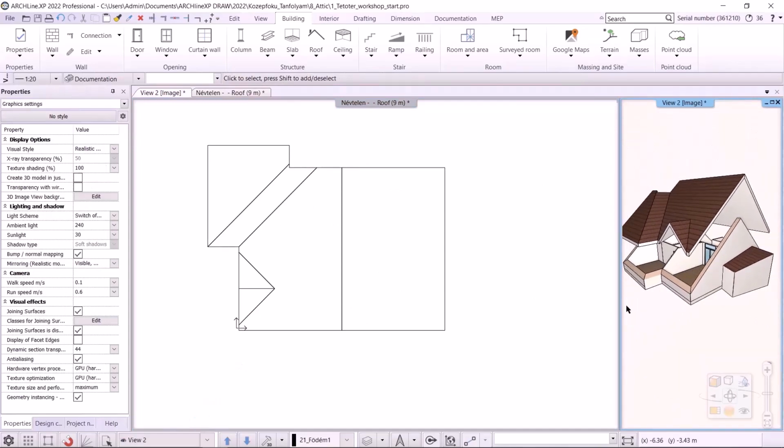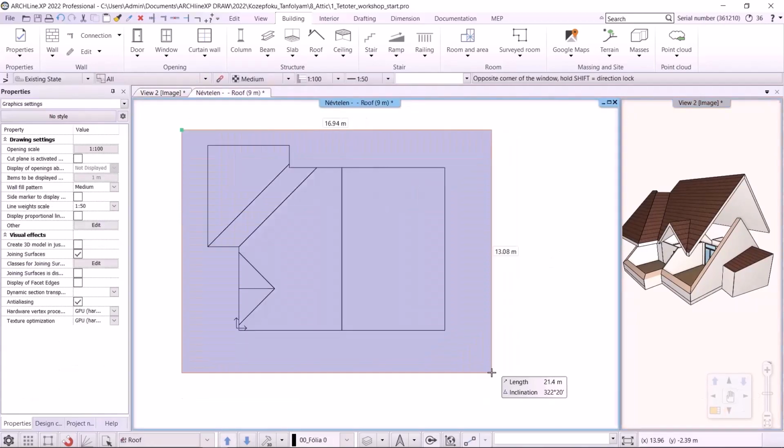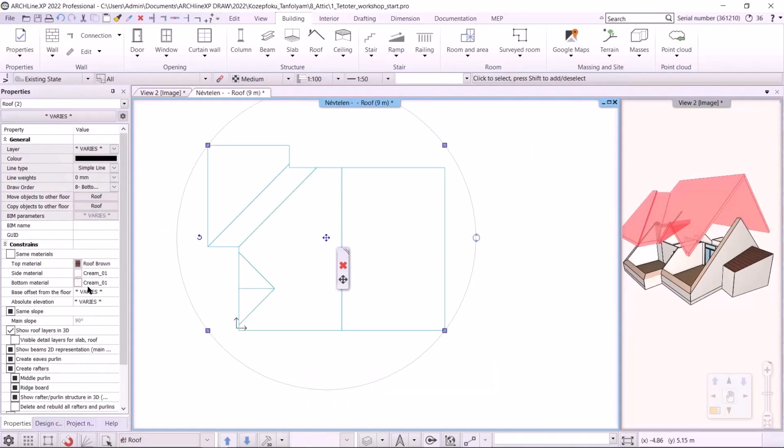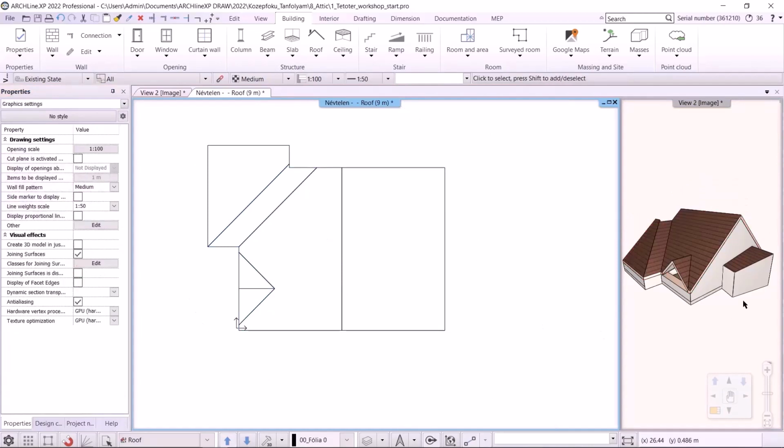So the roofs have to be moved down, but only by 2 meters instead of 3, as the height of the knee wall has to be subtracted. I select the whole roof and rewrite the relative height -2 meters. Now we can treat the levels as completely separate.